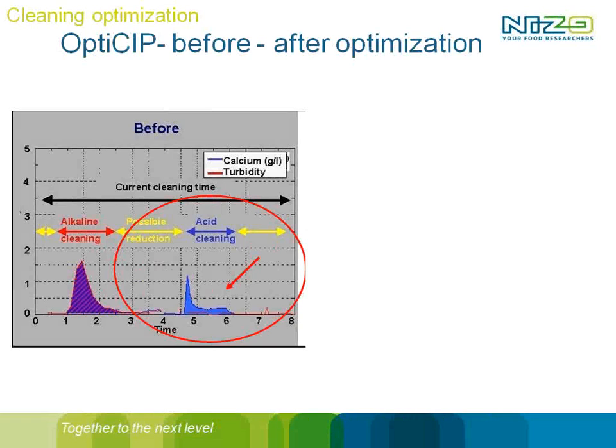What we do is we have a cleaning cycle, and during the cleaning cycle, each amount of time, for example each minute, we take a sample. And in the meanwhile, we're logging all relevant data. So what are the temperatures we're using, which valves are open, are we adding acid, caustic, or whatever, are we adding water, are there any other important features to be logged.